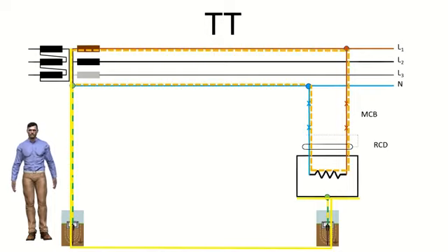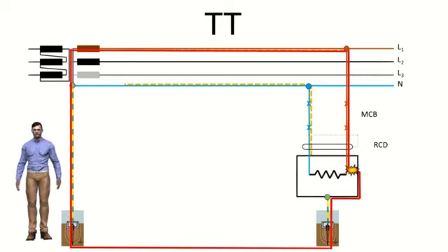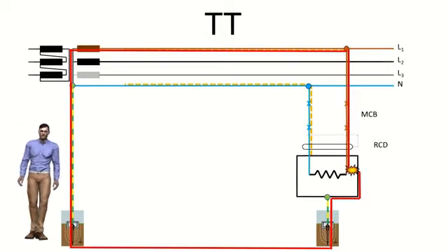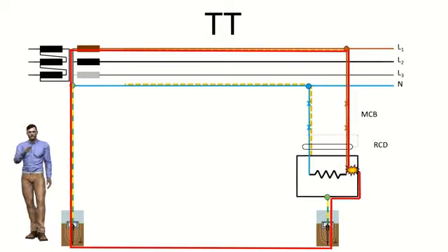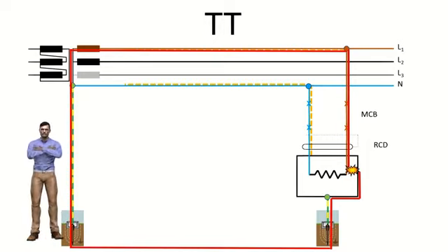As I have commented, under normal conditions the earth leakage current will be relatively small. However, in the event of a fault between a phase and the ground of an equipment, the current that appears to ground will normally have a lower value than the short-circuit current. In this case, the fault loop that we have, in addition to including metallic conductors such as the phase conductor and the transformer winding, also includes grounding resistors, which may have a more or less high value depending on the state of the stakes, whether it is summer or winter, etc. In this way, the resistance of the ground loop is not as low as the resistance of the short-circuit loop of active lines, but the currents that appear can be enough to cause the metal chassis of a load to be put at a dangerous voltage.